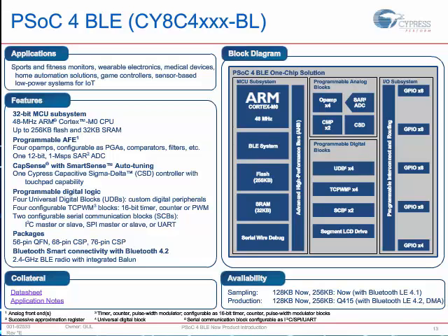The chip is also available in a couple extremely small packages. Recall the module was 10 millimeters by 10 millimeters X by Y. The chip is available in footprints as small as these 68-pin CSP or chip scale package, which is 3.5 by 3.5 millimeters. So if you have the expertise in doing your own antenna design, or if you're creating a product that is extremely small form factor, the module may not be the right bet for you. You may want to go with the chip and create your own extremely small antennas. And again, that's something Cypress has the expertise in doing, and we can help you through that process. The key point here being that the chip is available in extremely small packages, allowing you to create small PCBs.